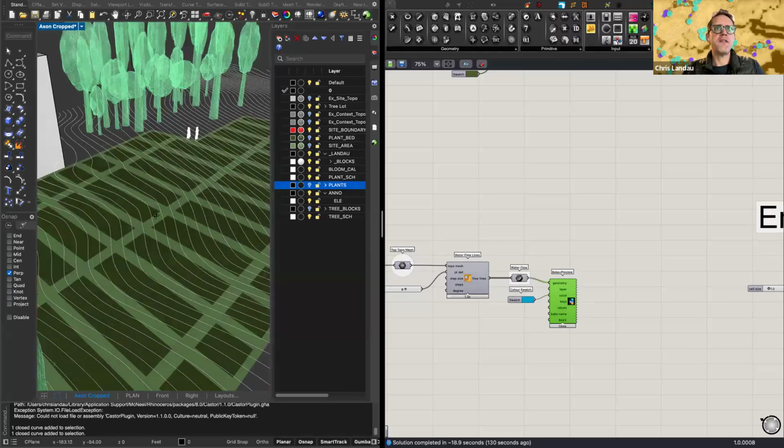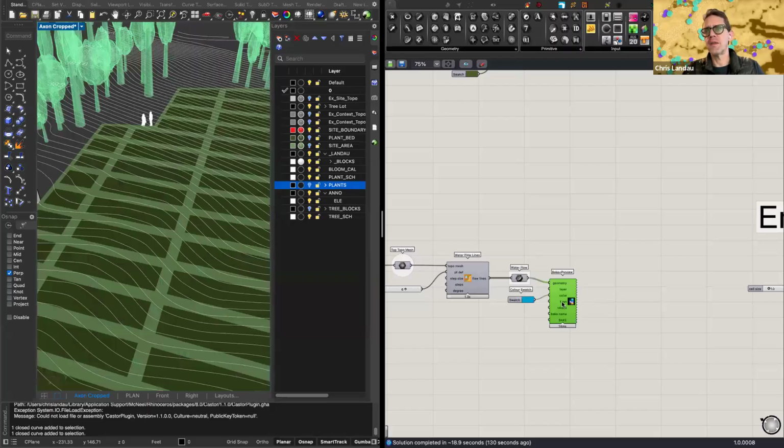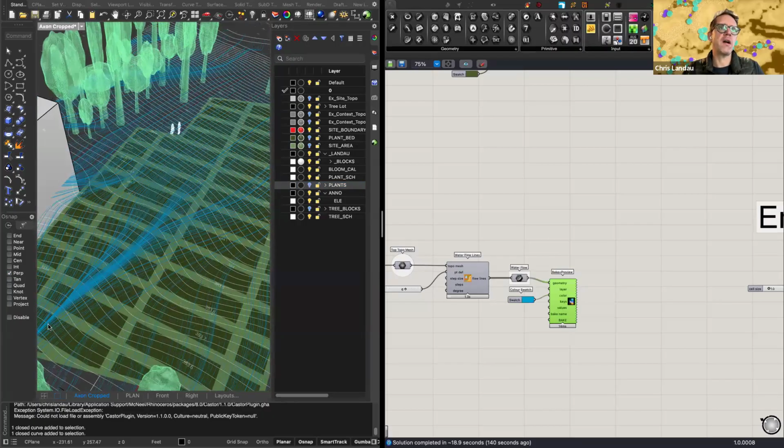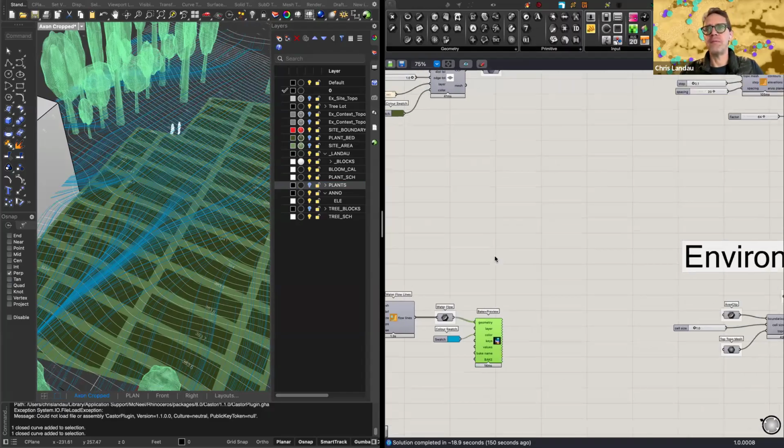But you can see how the topography is influencing the water flow. So if you just turn this back on, you can see that even just subtle topography can really channel water into a swale, just kind of how water works. Flat ain't flat. Flat's gonna turn into something else eventually. So how do we account for that?